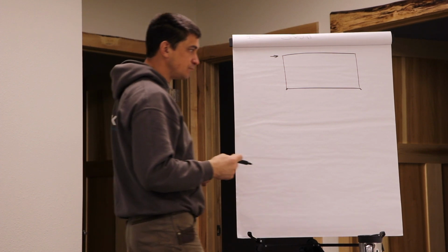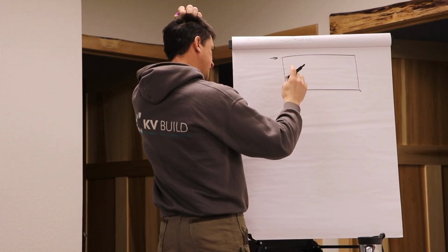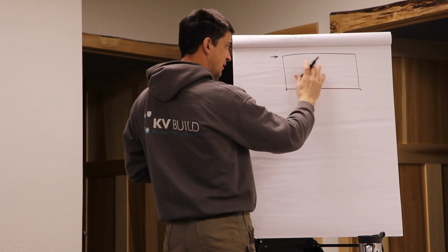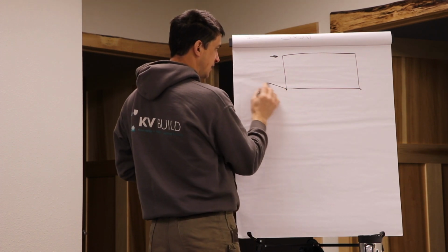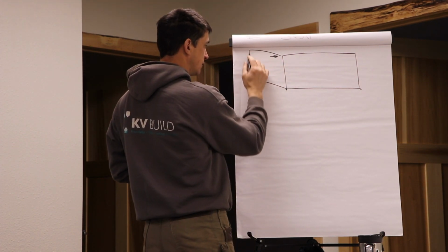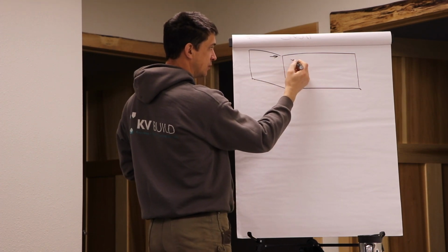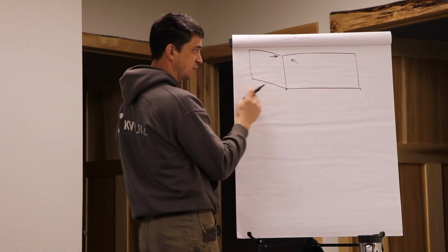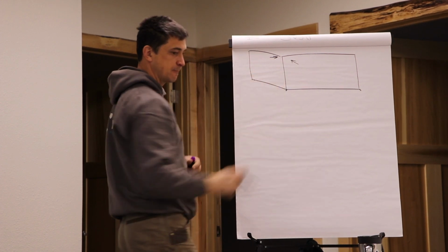And so if I have this surface braced, then it's rigid this direction, but that doesn't help with anything going the other way. So then I have this other wall going back this way, and if the wind blows on this surface and pushes it back this way, this wall isn't resisting that, this one is.